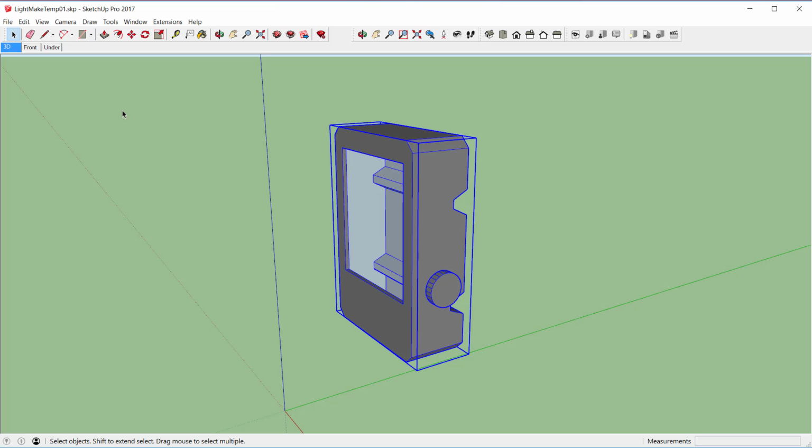The third and final object that we need for our new floodlight is the light source component, complete with the correct photometric definition. Before we start this part of the process, we need to measure the width and height of the luminous aperture of the floodlight model. Using the tape measure tool again, we measure 200mm for the width and 230mm for the height.